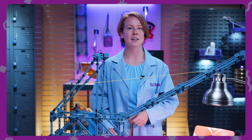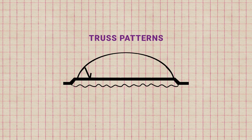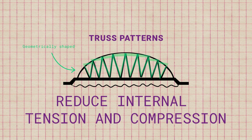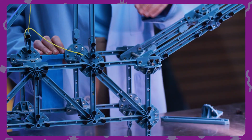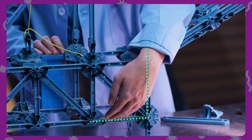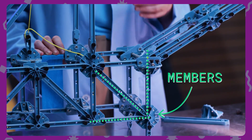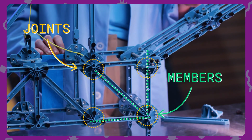Bridges can also be designed with truss patterns. In truss patterns, the beams are arranged in geometric patterns, usually triangles, to reduce the internal tension and compression that each member experiences. Here's an example of a crane with a truss design. The vertical, horizontal, and diagonal lines represent the members. Members connect at joints, and joints can be further broken down into 3 different types.